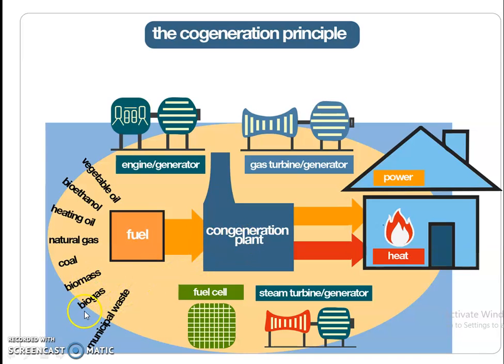Generally you know about biogas plants, floating type or fixed type. With the help of the Khadi Village Industries Commission, a digester uses cow dung waste or other slurries to produce methane gas, and you can run an internal combustion engine with biogas, whose major gas is methane. After that, from municipal waste or vegetable waste, through fermentation or anaerobic digestion, in the absence of oxygen, we again produce methane gas.